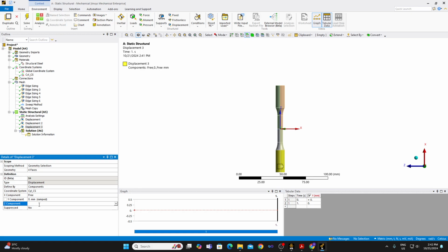Okay, so now the next thing that I'm doing is I'm applying a displacement in z direction. Once again, this is all with reference to the cylindrical coordinate system. The top part is fixed by the fixed crosshead. The moving crosshead is pulling the bottom portion, and how much should we pull? A typical ductile material will elongate, let's say, about 20-25%, and in simulation it would probably go even further. So let's say we can extend the specimen up to 30% of its length. That is what I'm anticipating.